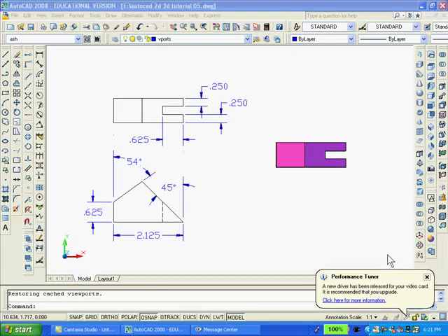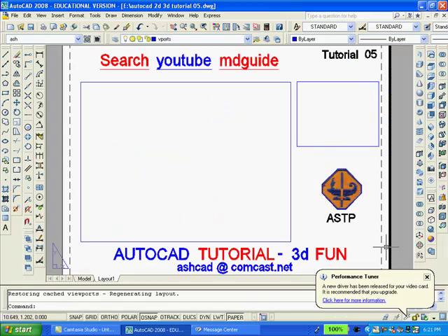Having finished constructing the 2D solid model and dimensioning, I want to get back to Paperspace so as to view the drawings properly and make it ready for printing. So I'll click on the Layout 1 button. As you can now see, my template rectangles are still there. Now to create the two viewports, I'll type MView, enter, and select two diagonal points to create the larger and smaller viewports.